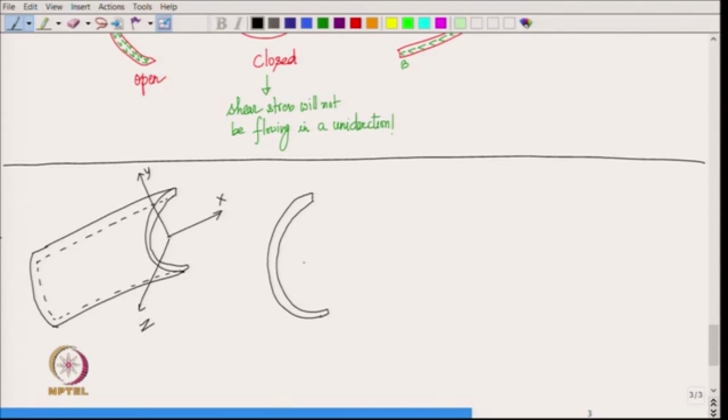And then in the cross section we have got y axis and z axis, and since we know that the shear flows from one end to the other, we can define an arc length along the cross section. So, suppose that we run an arc length coordinate starting from one end and denoted by S. Okay.